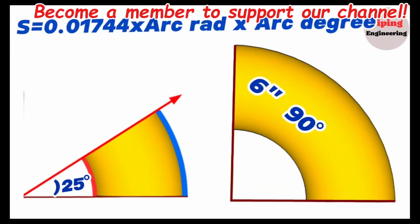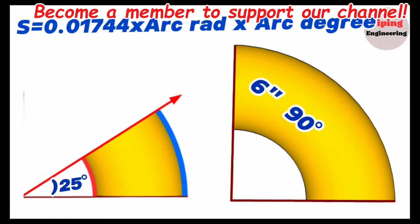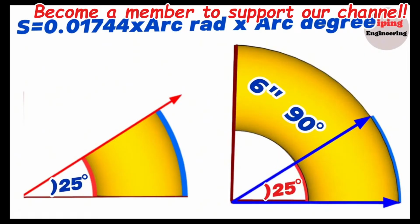Applying this method, we can calculate the lengths of the elbows cut at different degrees from the outside and inside. Let's learn how to mark and cut a 25-degree elbow from a 6-inch 90-degree elbow using this formula. We first measure and mark the distance from the outer upper edge of the 90-degree elbow to the length of the 25-degree arc.